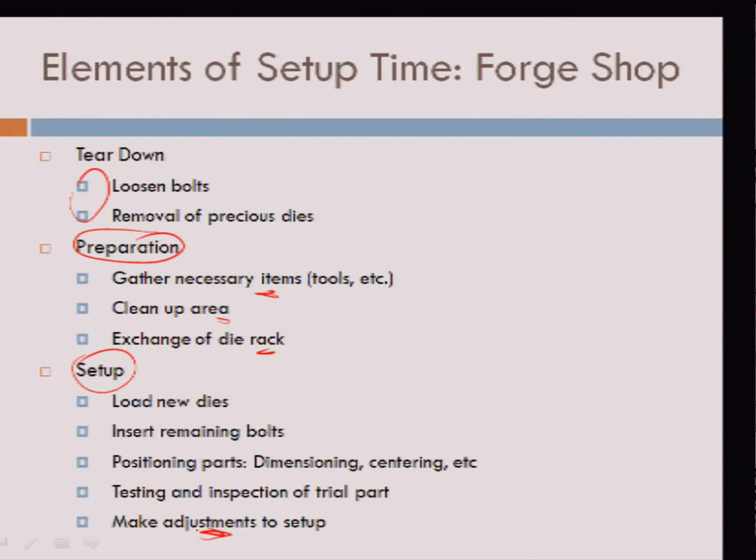So this is basically the first thing in any kind of process improvement activity. So even tooling analysis, the fourth stage in Burbage's powerful method of production flow analysis, this is what you would essentially do. You look at the elements of setup of the equipment, and then you try to associate those elements with design features, tooling features of the various parts which will be run on that particular machine.